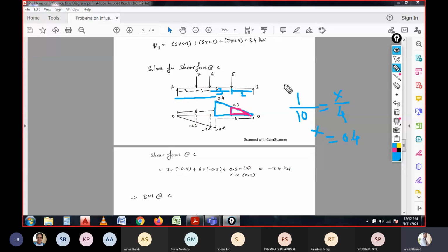So now if you write for that, how it will be: 0.4 divided by 4, which is equal to x, because this is unknown, this value we are now calculating, divided by 2, because it has the base length of 2 meter, right? With this equation x can be calculated as 0.2. So this is how the coefficients are calculated.